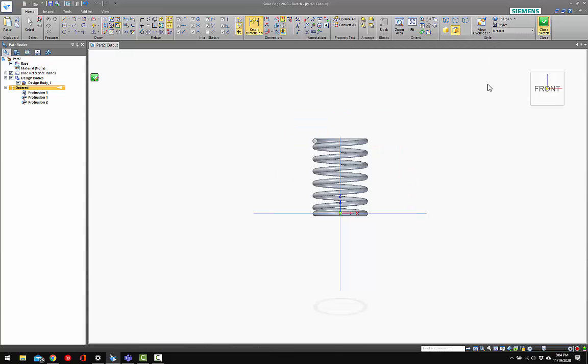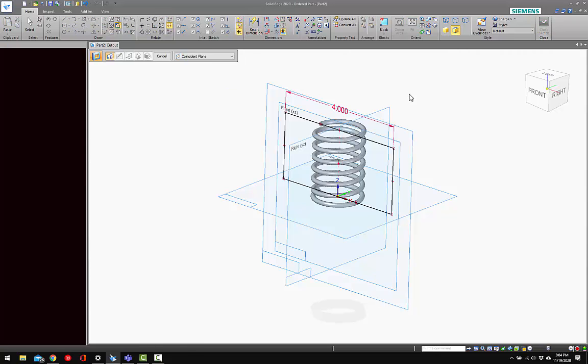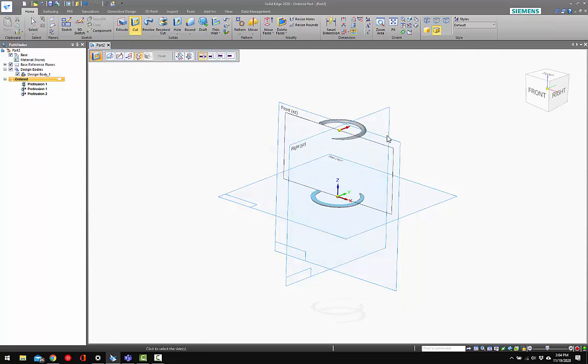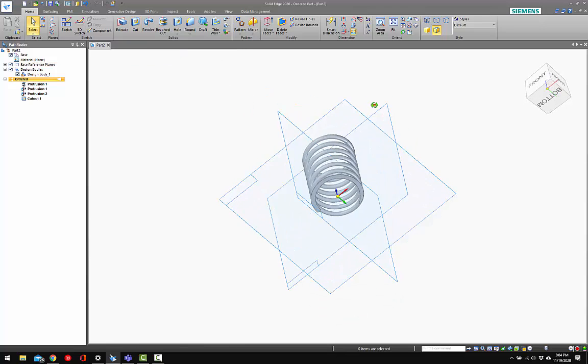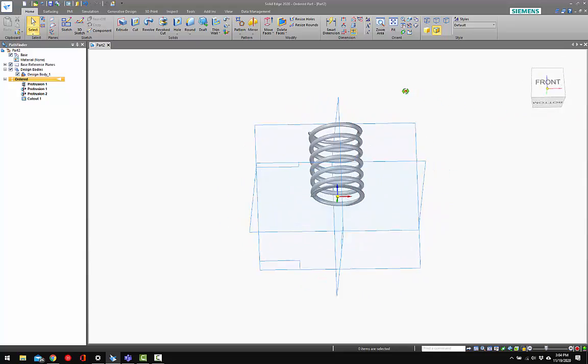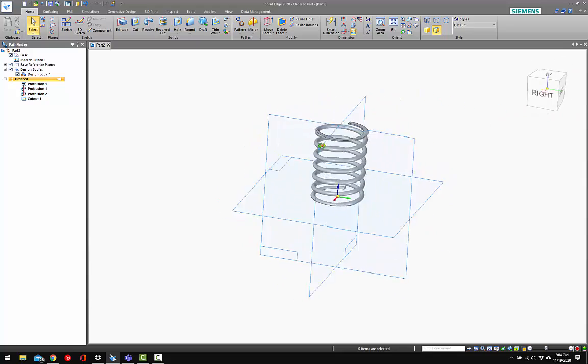All right, now when I do the cut, I'm not going to do a normal cut where I'm cutting to the inside, because then the inside of my spring goes away. So we're going to click here, and we want to cut to the outside, and I want to do through everything both ways. So now I have a proper ground and closed spring.